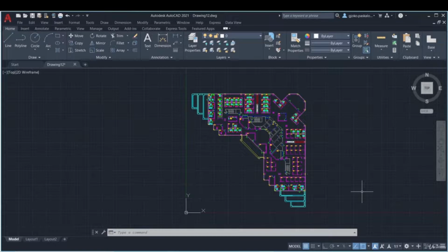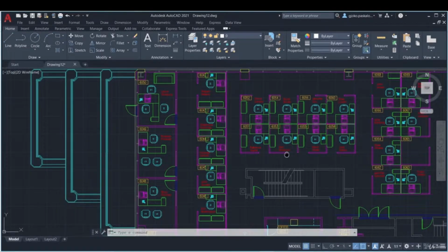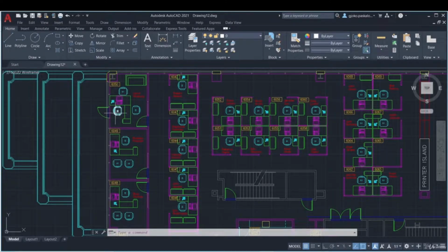Okay guys, in this lecture I'm going to show you how to deal with attributes, how to modify them and visually inspect them. For that I've inserted this drawing here, and if I zoom in you can see that all the text input actually is attributed text defined into a block. If I want to deal with attributes, I will go in this section here, and the modify tool is this. So I'm able to select a single attribute, and let me select one just to see.